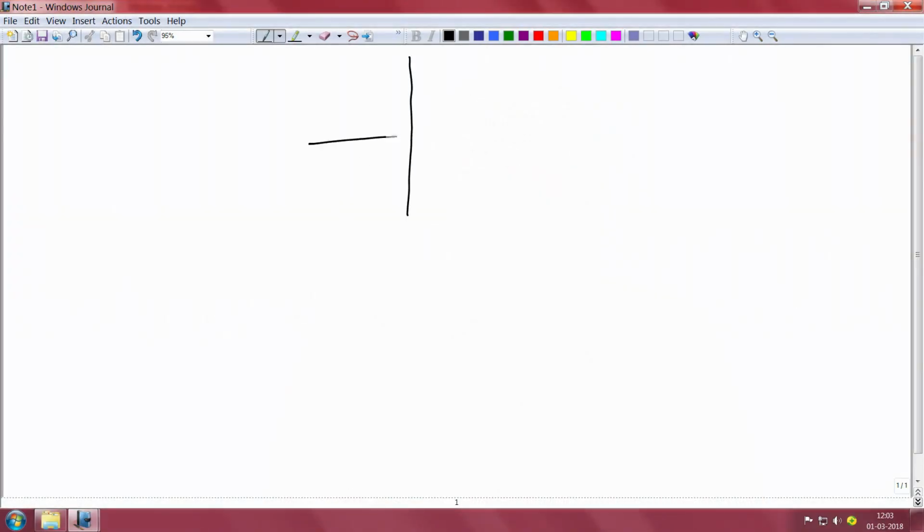Now in general let us assume that the Nyquist plot for our plant looks something like this. This is the real part of G, this is the imaginary part of G. The exact shape is dependent on the exact structure, but for the moment I am assuming that this is the kind of shape that it might have, and it so happens that in this case it avoids the critical point